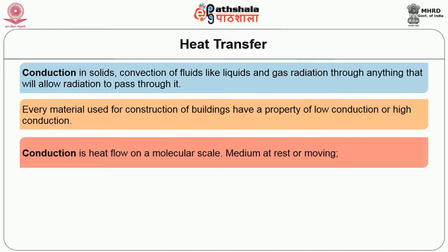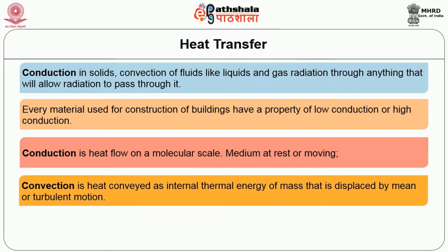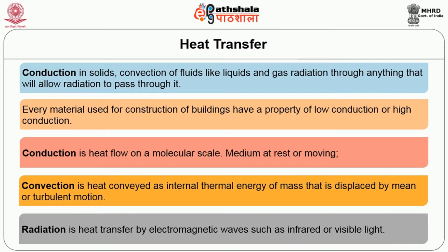Conduction is heat flow on a molecular scale, in a medium at rest or moving. Convection is heat conveyed as internal thermal energy of mass that is displaced by mean or turbulent motion. Radiation is heat transfer by electromagnetic waves such as infrared or visible light.